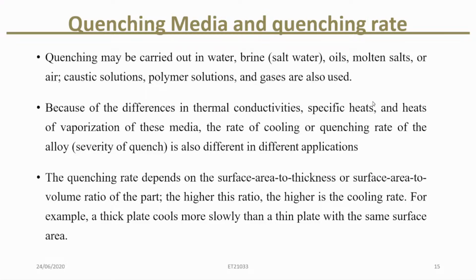Thick blocks cool slower, even if the surface area looks similar. As an example, a thin plate hardens quickly, and a thick plate cools slowly and needs a more severe quenchant or a different process to reach the same hardness without cracking.